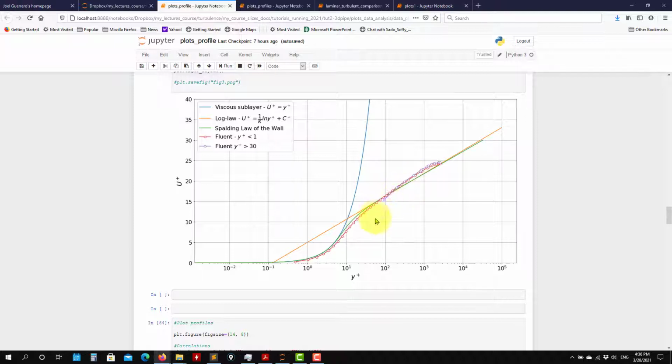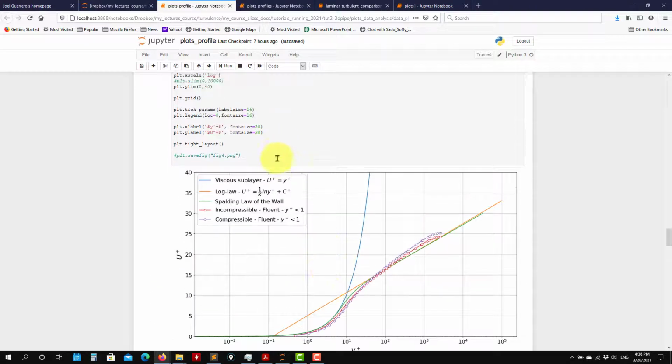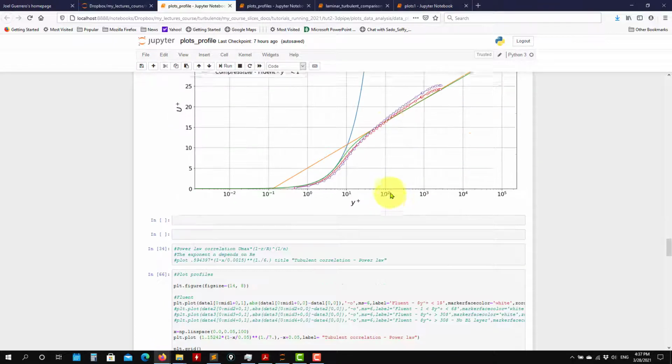As I mentioned, with the wall function, see that you put your first node far from the wall, okay? So this is about 100, and you are saving all those cells here, okay? And they work remarkably well. So see here that we're close to this logarithmic law, so they work very well, okay? So you have the plot there, and then in this one we compare the compressible solution with the incompressible one, okay? So remember that in the compressible one now we have actual density, viscosity values, larger velocity, but disregarding that, we should always reproduce this profile that you see that we have there, okay?